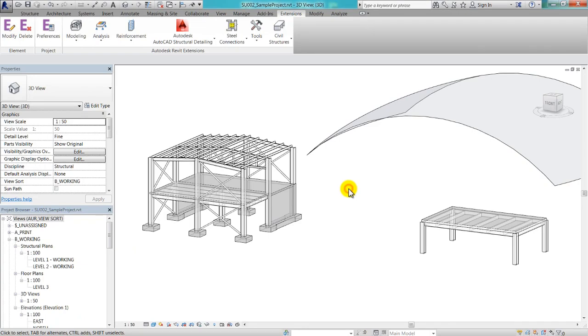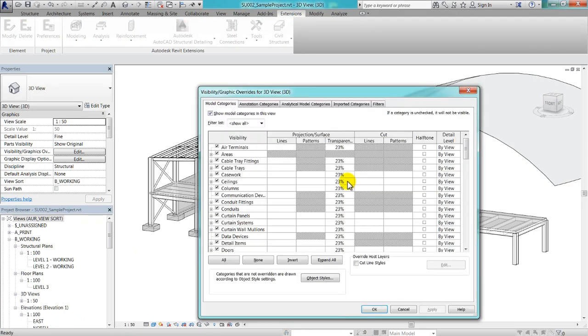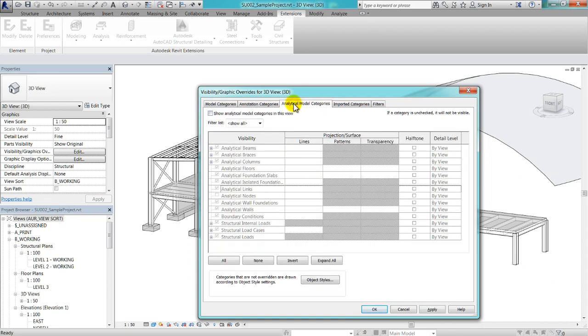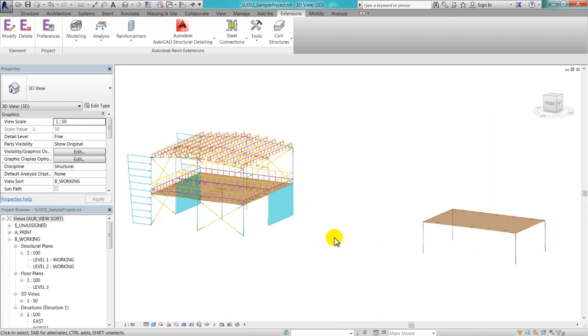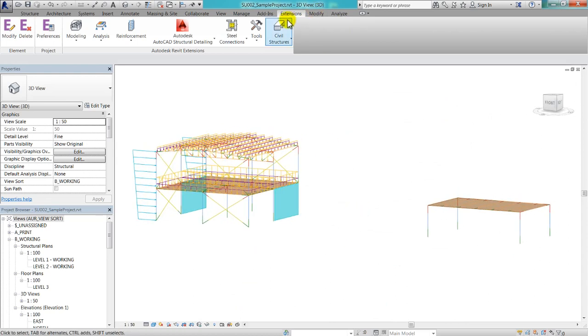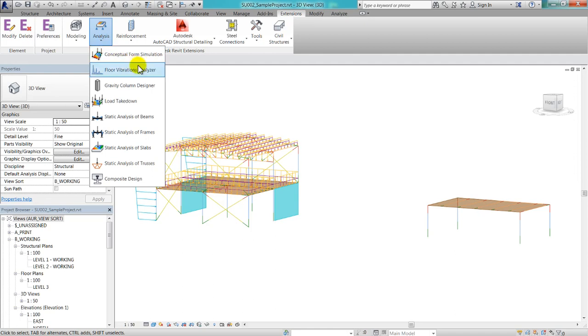Revit not only provides the user with an analytical model to send data to dedicated structural analysis software, it also provides some embedded analysis functionality. This exercise is going to introduce the embedded structural analysis tools and how to operate them. All these tools have in common that independent verification has to be done prior to relying on the results. Some of the data input can be confusing and some modules display inconsistent results.